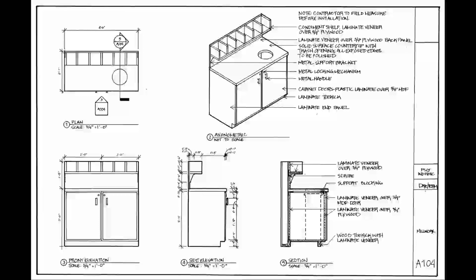We've got the exterior profile line that's nice and thick, our thickest line weight. Change of plane line weight is medium. And then you can see here where I had to get into this area, I ended up having to use the thinnest line weight to create the knobs and the locking mechanism. Once I felt like I had some more control, I was able to go over it with the thicker line to create the profile.